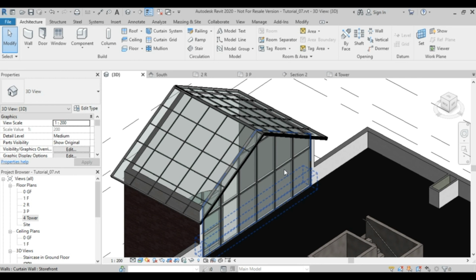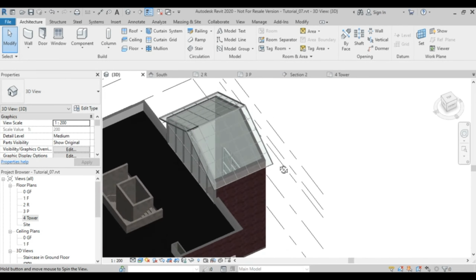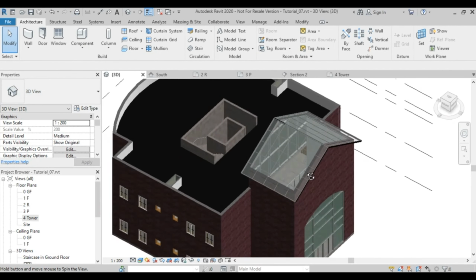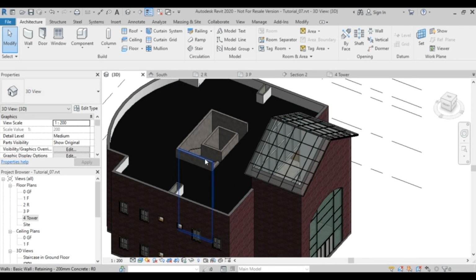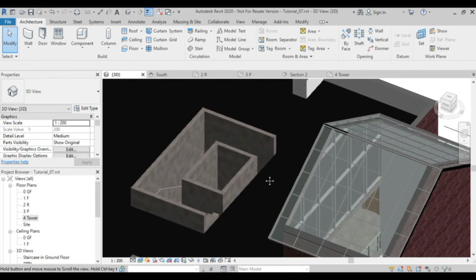Great. What else can we do? Okay, we have the roof, and we have the shaft of the floor, shaft of the staircase, shaft of the elevator hanging over there. What we need to do is the following. In order to install doors and make sure that whoever is climbing up is not striking his or her head on the roof, we need to increase these walls' height.